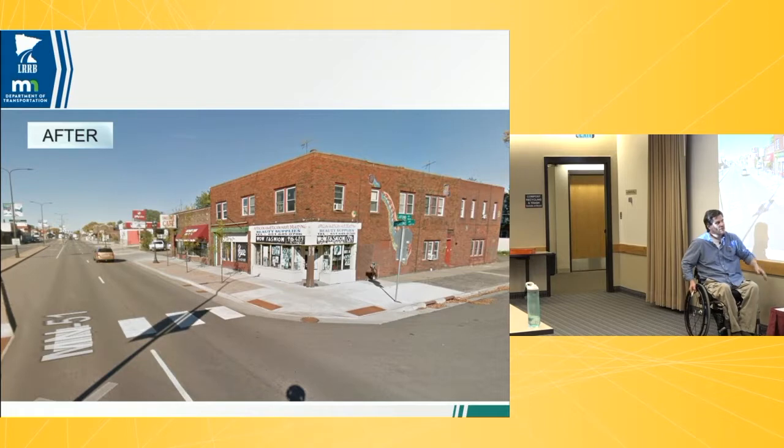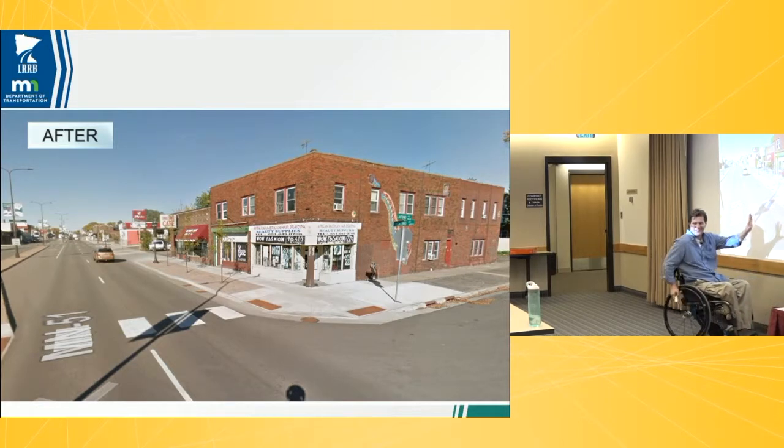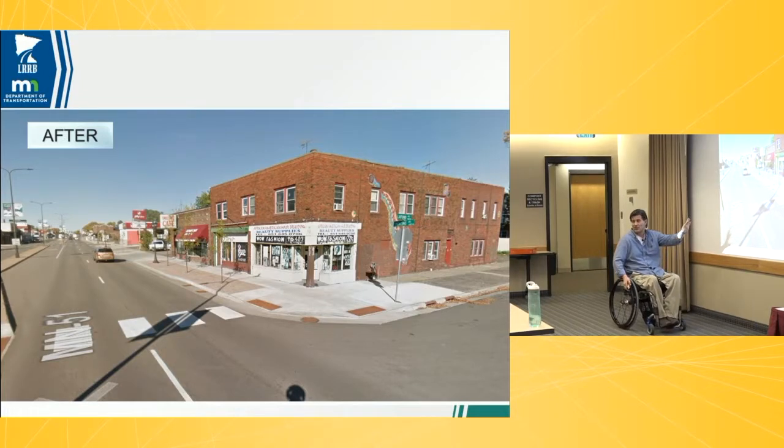But that's actually how trucks use this area. They turn from over here, right in front and into the lane. So it's kind of a crude compound radius, but it's just making it fit what was there and getting the curb ramps to work within the existing infrastructure, because we couldn't go out there and start moving every structure.